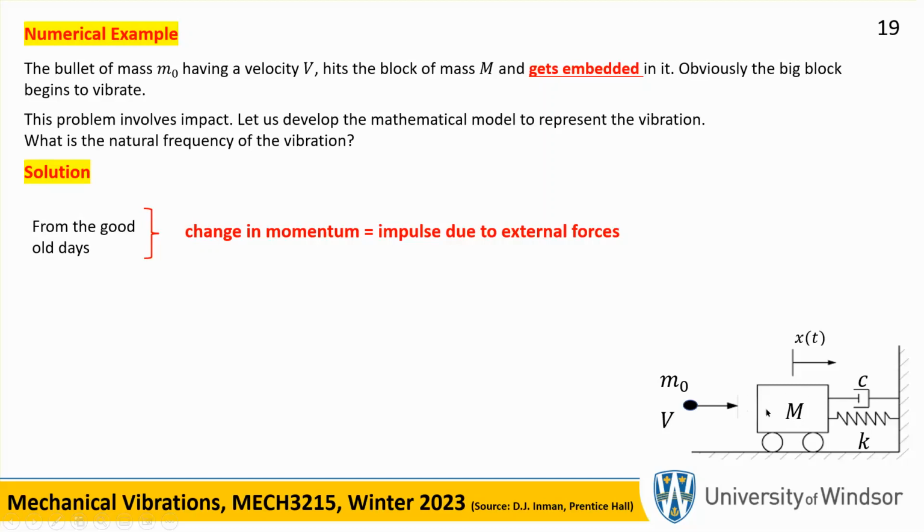But these are the same forces, these are internal forces. In this particular problem, although there is an impact, there are no external forces during the embedment of the bullet in that block. Yes, later on, of course, you have force of the spring, force of the damper, but that is not during the initial embedding of the bullet in the block.